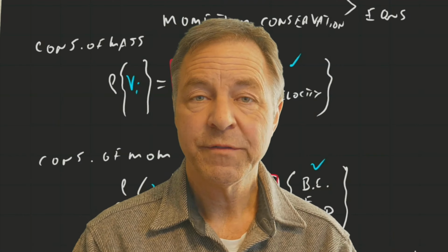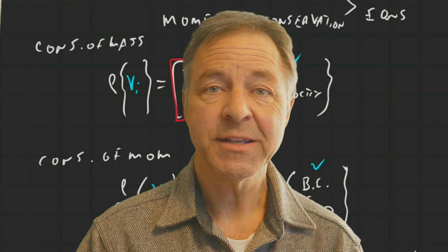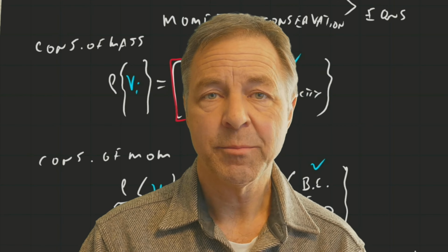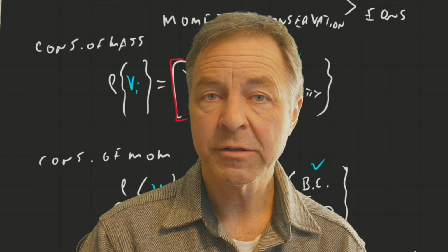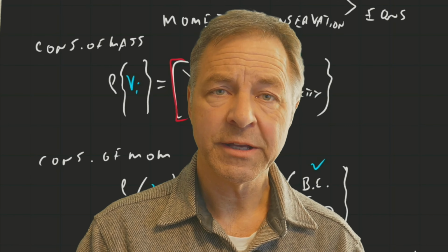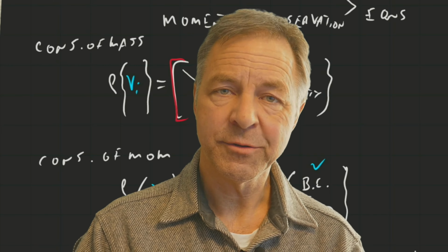There, we've added the two-dimensional shape of the NACA 0010 airfoil into Solidworks, and we've created a long, slender airfoil as a solid. In the next video, we'll move on from there and do some flow simulation.